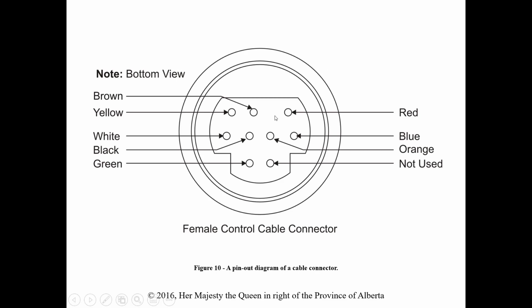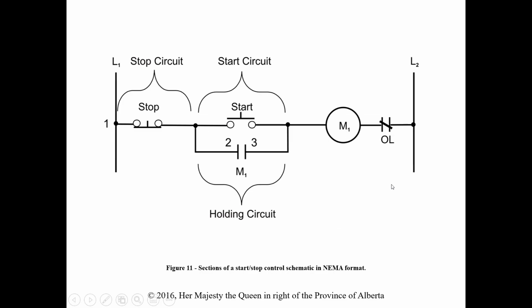This is a pinout, same kind of deal, where we just know, hey, the yellow wire goes here, white goes here. Again, you don't need to have any understanding of the circuit or what's happening. As long as you have a pinout, you could literally sit at your desk and make 600 of these, and they would be correct. This would be like for a military connector or an Amphenol connector, that kind of deal. So you could have somebody sitting and making these up and not know anything about the circuit at all, and we can use an interconnection diagram to do that and still be 100% correct in what we're doing.